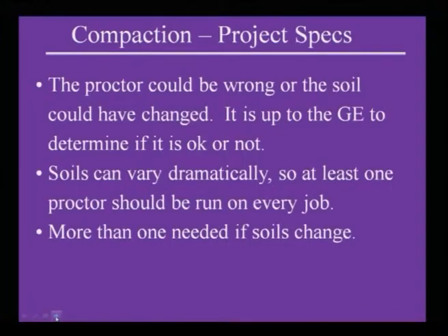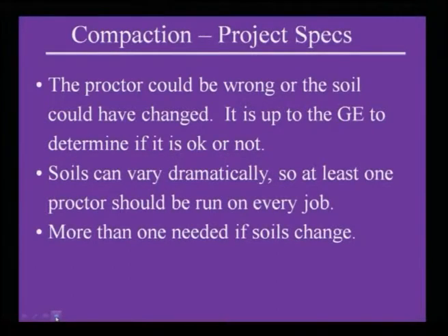The Proctor could be wrong or the soil could have changed. It is up to the geotechnical engineer to determine if it is okay or not. It does not mean that the Proctor compaction test will give an accurate result. It may be wrong, it may be right. Only the geotechnical engineer decides based on your laboratory study. Soils can vary dramatically, so at least one Proctor should be run on every job. More than one is needed if the soil changes.